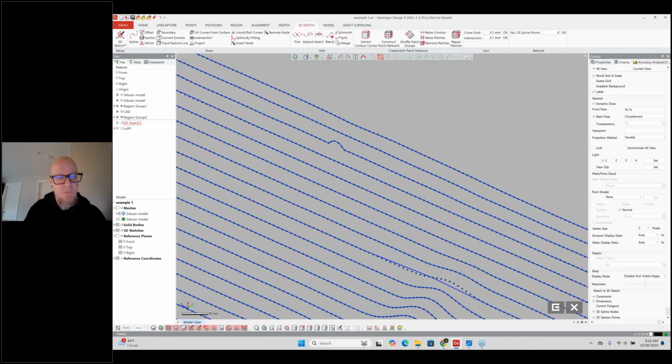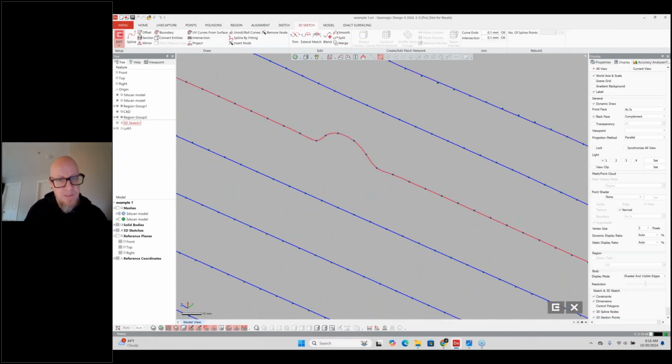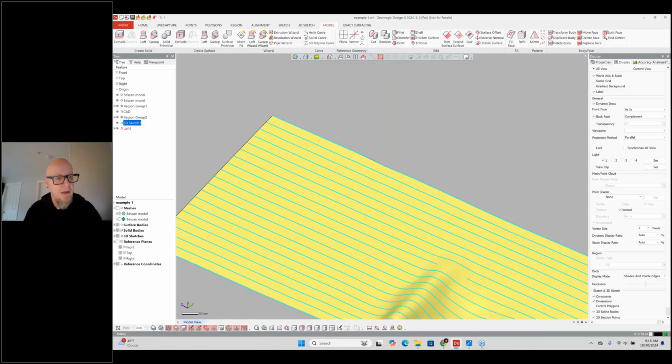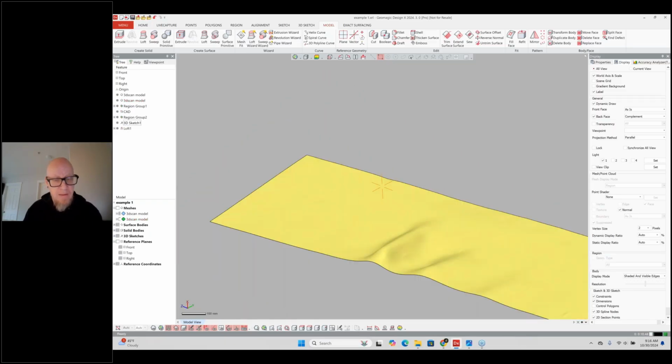And then I will give a big zoom here. We have a few points, and I will select these points, only the points you don't want. And I will hit the delete button here. Okay, I deleted these four points, and I think that will be enough. Okay, and then let's leave edition. And as you can see, I don't need to generate a surface or anything. Always there. And then we don't have the bump anymore.